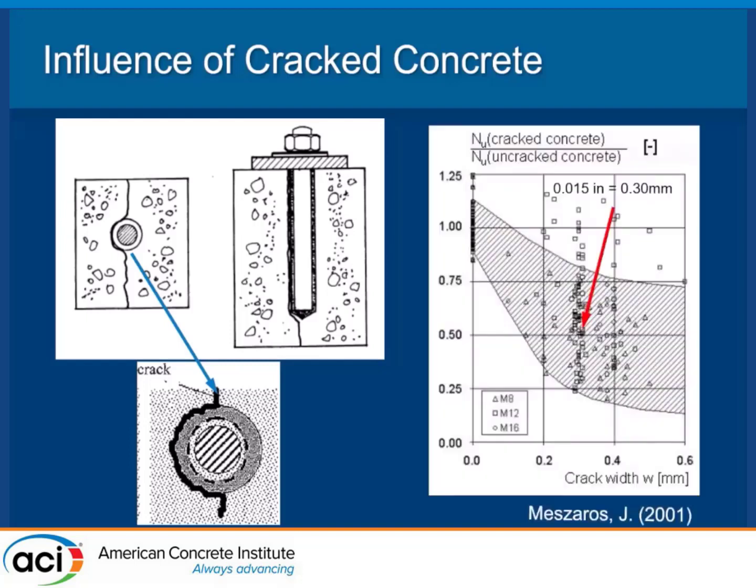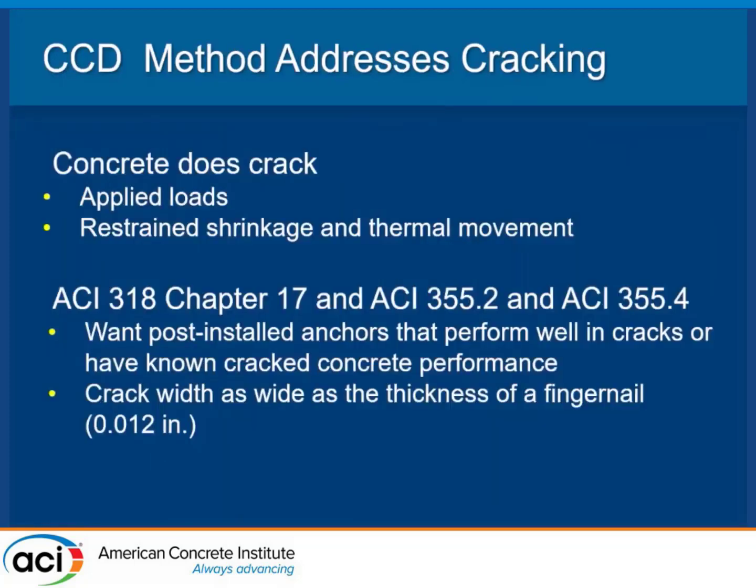Sorry, you're going to get this a little bit. I didn't know what kind of size screen I was getting, so I went to a shorter screen and I didn't catch everywhere the movement of my little arrows and things like that. This arrow is actually supposed to go over here to the edge, but in essence, at 0.015 inches, we basically go to 50% of our capacity for, which I already talked about, adhesive anchors.